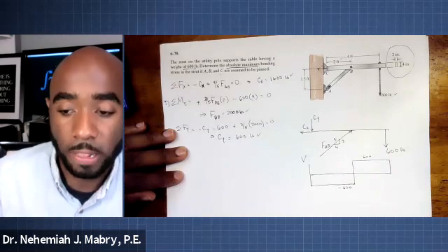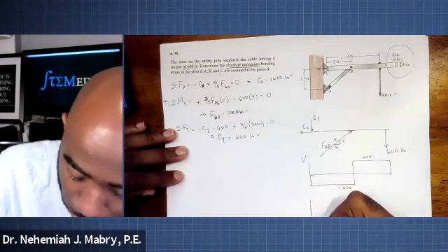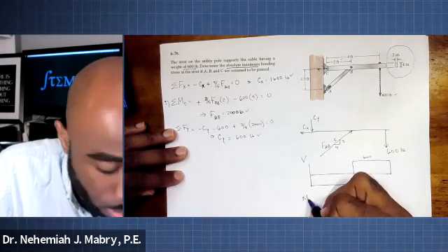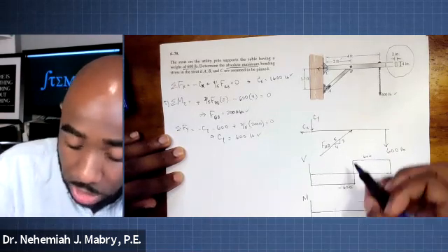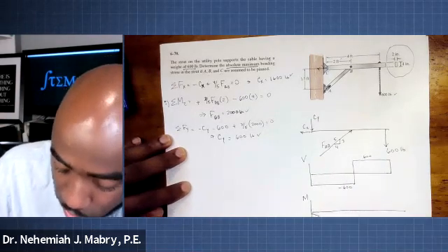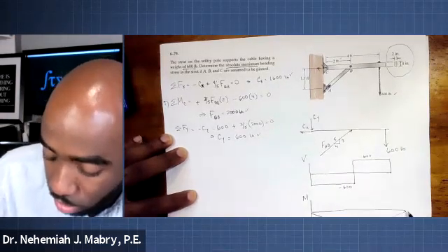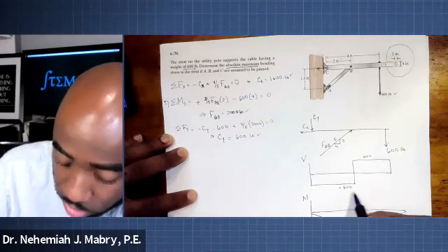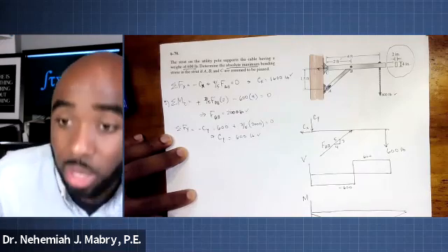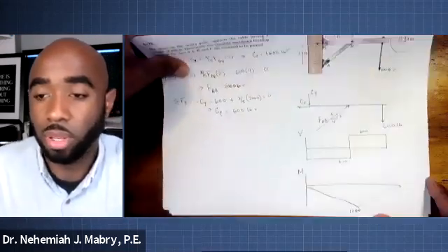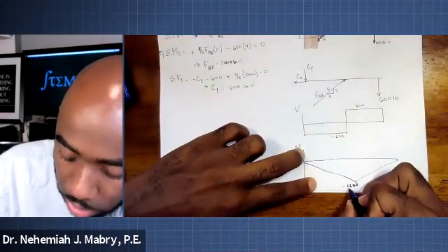So what does that mean for our moment diagram? Well, our moment diagram should be straightforward and easy to draw. It's going to start off going down negative. So 600 times 2 means 1200. So it's going to go down linearly. And then up here, it's going to come back up linearly. And this value here is 600 times 2, which is a negative 1200. Let me make sure that's in frame for you. Boom. Negative 1200 is what your moment diagram will give you right there.